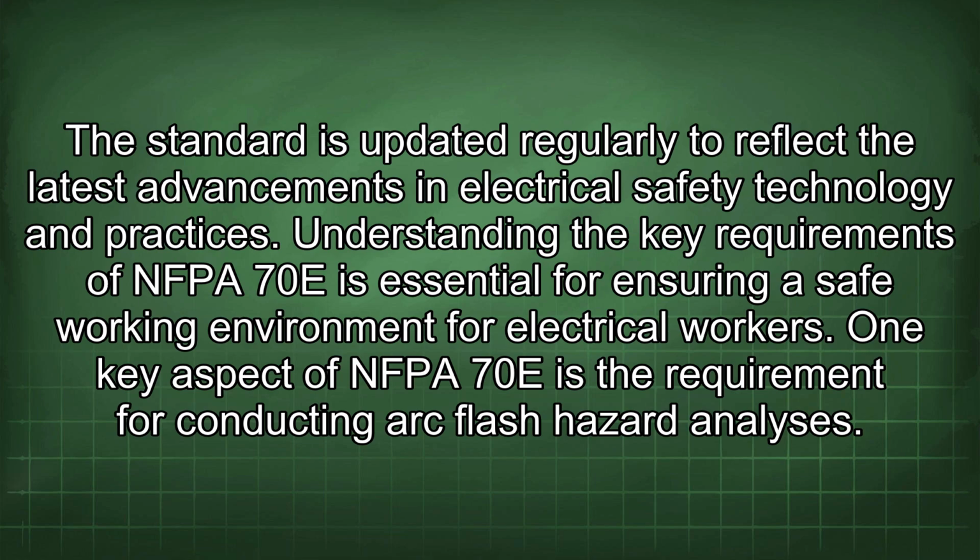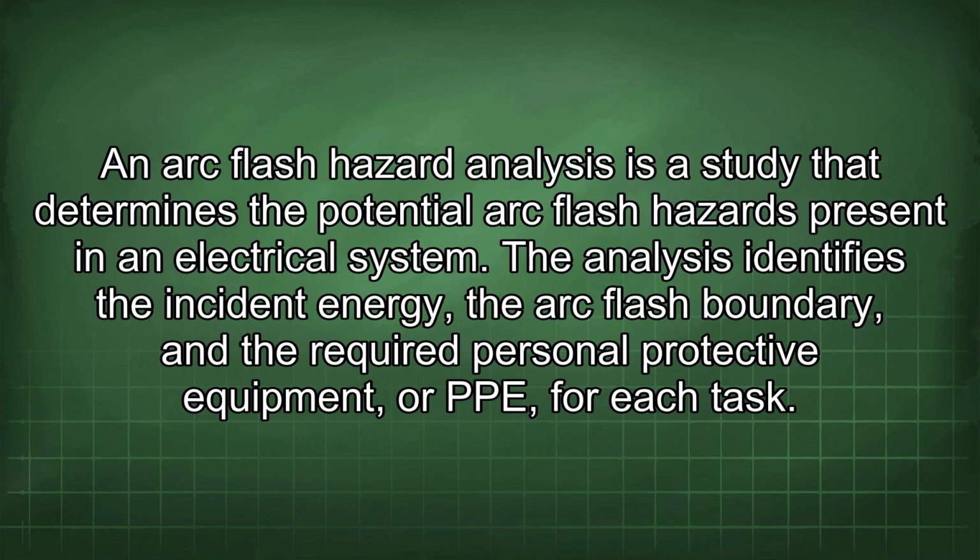One key aspect of NFPA 70E is the requirement for conducting arc flash hazard analyses. An arc flash hazard analysis is a study that determines the potential arc flash hazards present in an electrical system. The analysis identifies the incident energy, the arc flash boundary, and the required personal protective equipment, or PPE, for each task.